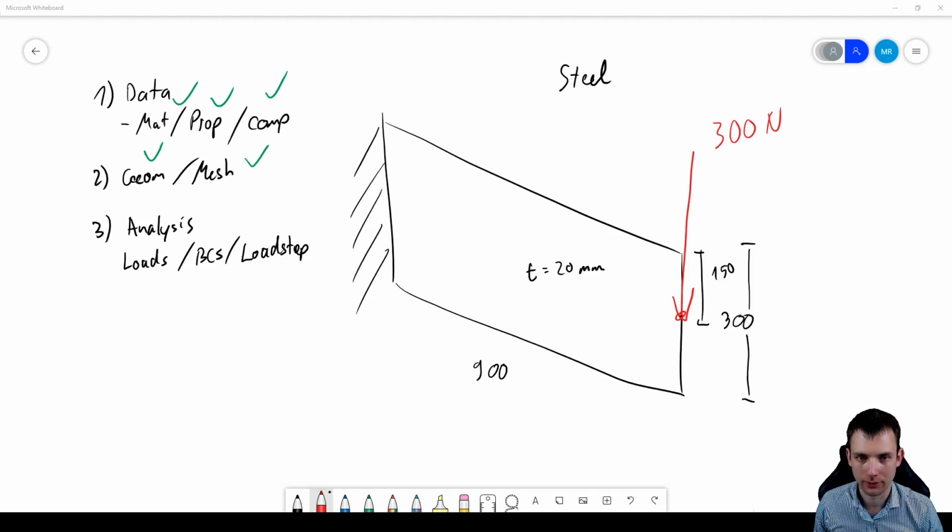Okay, so selecting the load, in this case it's this one right here. Why is it not selected? Okay, that's strange. I deselect it again and select just the one here, that's okay. And then we have -300 and the direction is the y-axis. So it's pointing downwards. Create it, and as the next step, we want to do our fixed boundary condition.